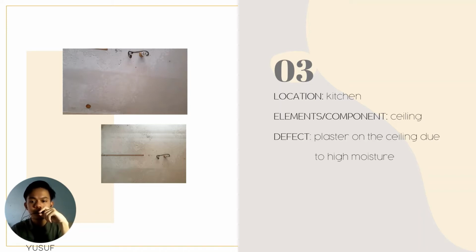Remove the damaged plaster and other damaged materials. Seal the water damaged part using quick dry primer sealer and wait until it dries for a few hours. Repair the plaster using several thin coats of joint compound to fill in the missing plaster. Apply a second coat of joint compound on the deepest part of the damage. After it dries, use sandpaper to make it smooth. If necessary, paint the ceiling to match its original color.